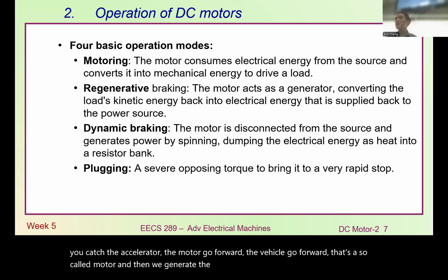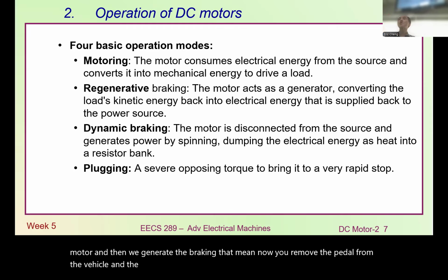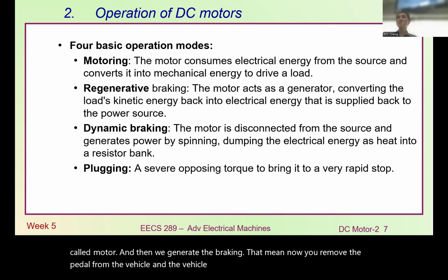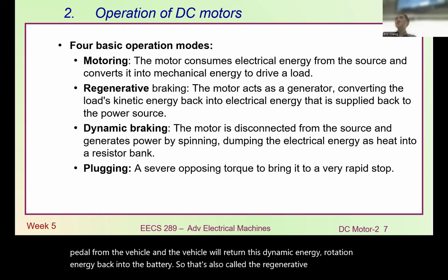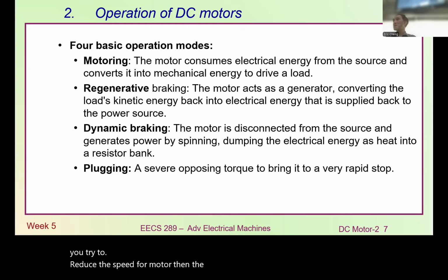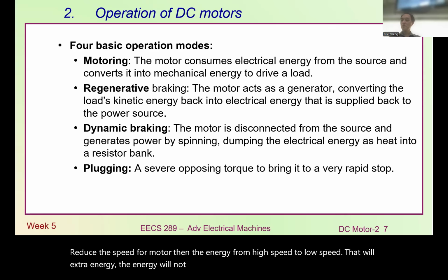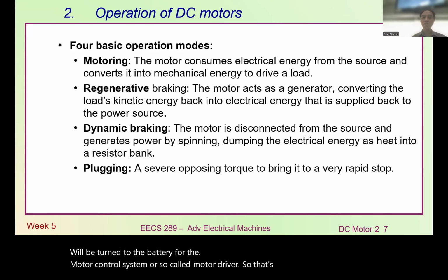And then we have braking. That means now you remove your foot from the pedal, and the vehicle will return its kinetic, rotational energy back into the battery. That's also called regenerative braking. When you reduce the speed of a motor, from high speed to low speed, there will be extra energy. The energy will not disappear; it will return to the battery through the motor control system, the so-called motor driver. That's called regenerative braking.